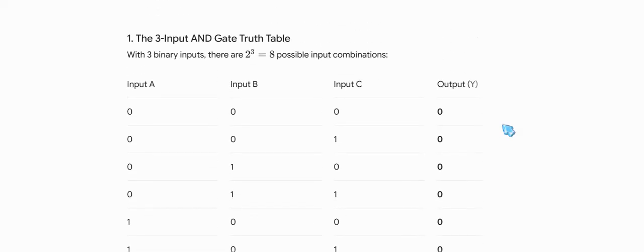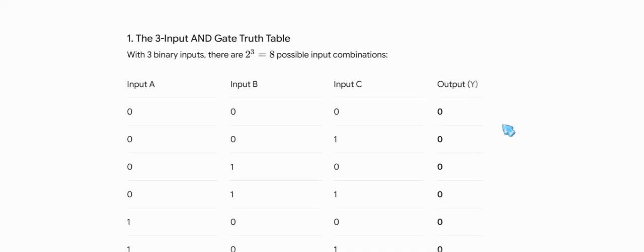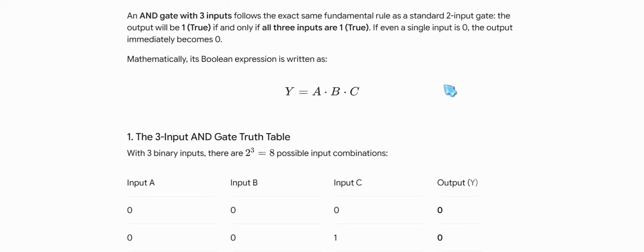And then again the same thing you follow with the OR gate also. All right, so keep revising, and you try the truth table with the four input AND gate. If you know the truth table, drawing the picture is not very difficult, and this is the way how we present it. This is the output, means A into B, actually this dot is the symbol of the AND, and you can consider it as multiplication, so it will be easy.